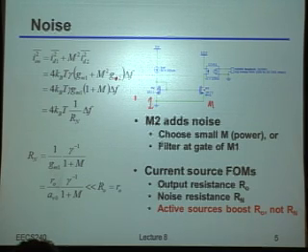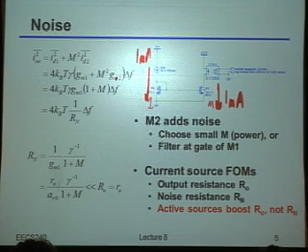Yeah, just make m small, right? So if I make m small, then whatever this multiplying factor is will just be a smaller factor. Now, why do I tend not to want to do that? What's the obvious penalty? Yes, which is written on the slide. Yeah, you have to spend power for it, right? Because obviously, if I said that this thing over here has to be a milliamp, and I make m 1, well, now I'm spending 1 milliamp over here. Why am I upset about spending 1 milliamp on that left-hand branch over there?